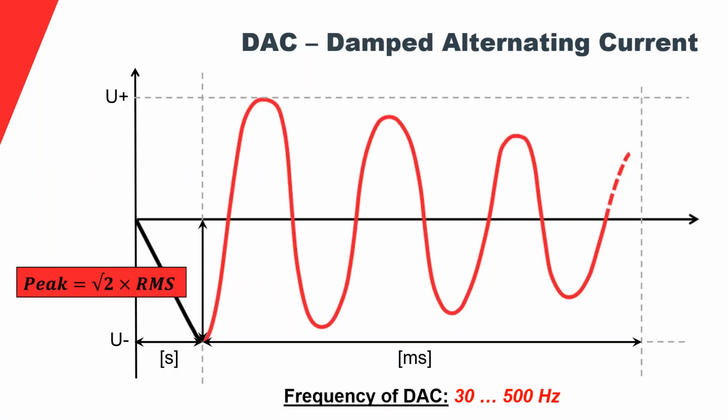Now, in terms of waveforms, the standard waveform for doing PD testing in the field is damped AC. Pretty much early on, since the 2000s, it was the first waveform that was proven, also by a CIGRE working group and by CIGRE publications supporting the IEC standard, to actually be comparable to power frequency.